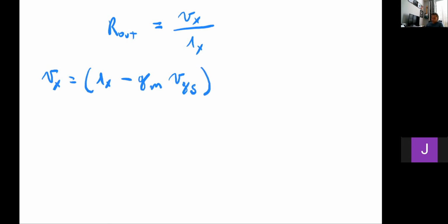It is biased, but with 0 volts, times the output resistance plus the current times the resistance at the other end, at the source of the common gate. So this is the same type of equation that we did to calculate the input resistance, but we're just looking at it from the other end. But it's the same type of rationale or analysis, okay?